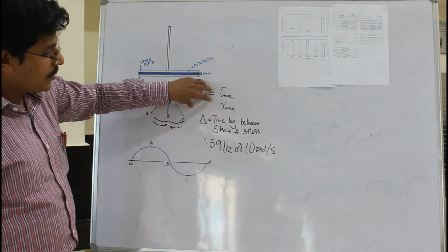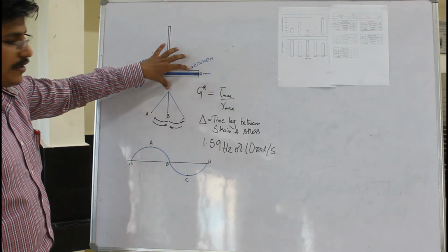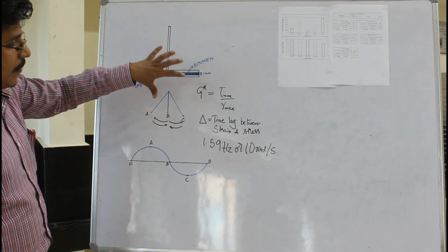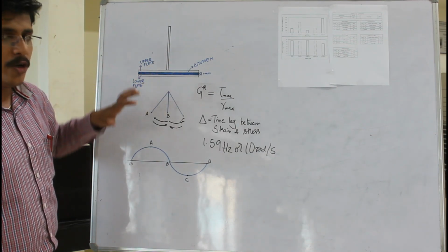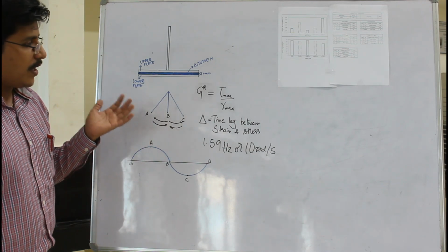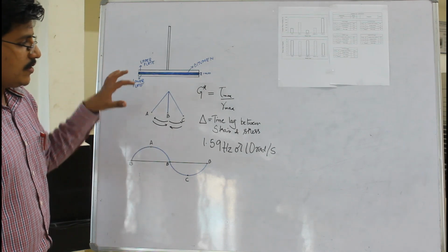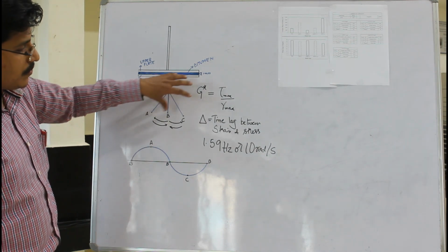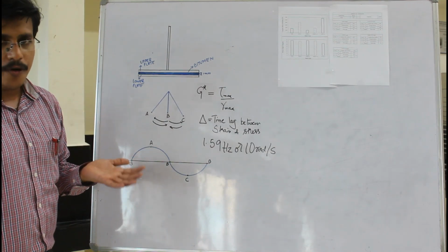We will talk more about this in theory classes. So this can be determined using the oscillation test. We will see the results of the bitumen we studied in this test. We studied three bitumen: VG30, CRMB 55 and PG 82-10. We will see the values we got for the three bitumen and how they compare after RTFO aging.